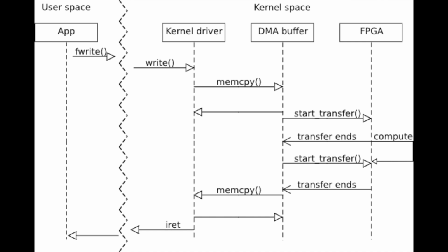The other device file instead exposes the DMA interface that we developed custom on the FPGA, among the various IPs we designed and deployed on the FPGA. Using two different files lets the user, for example, write the buffer multiple times and send a whole chunk of data in just one transmission, so potentially increasing the bus transfer rate.